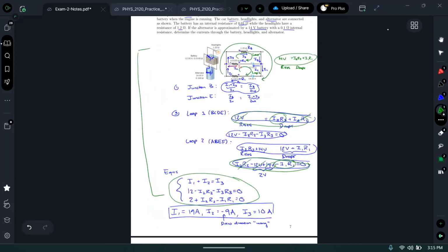So this example here is one case where you don't have series or parallel resistors. And so we have to apply Kirchhoff's rules. We do the junction rule first, look at currents entering and leaving junctions. We use that to label our resistors based on the direction the current flows. Conventional current always flows from high to low potential. That lets us label positive and negative here.